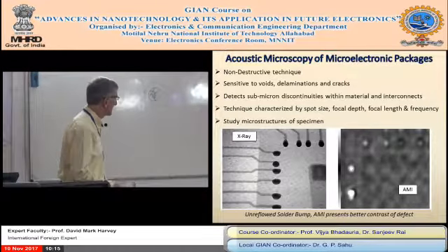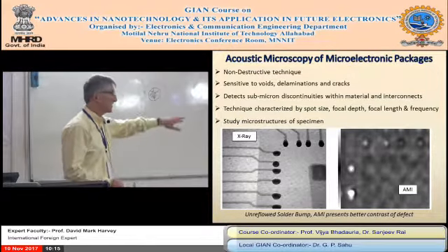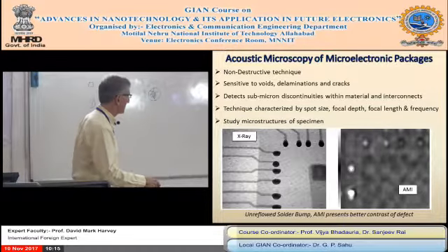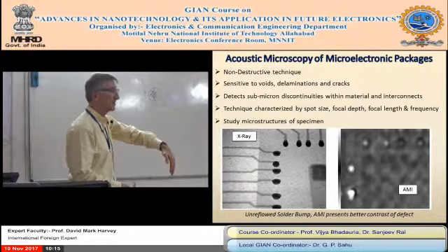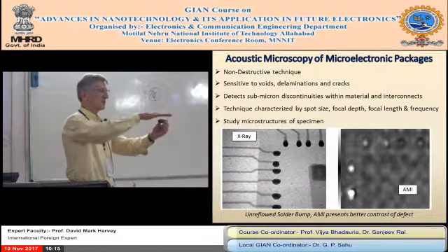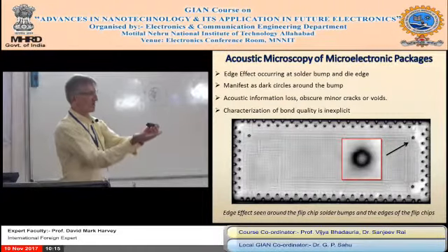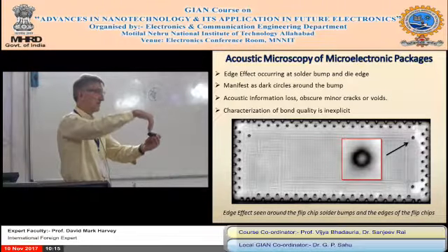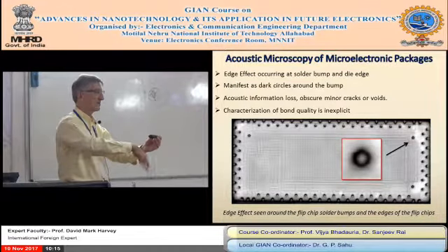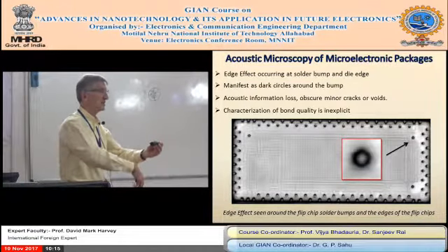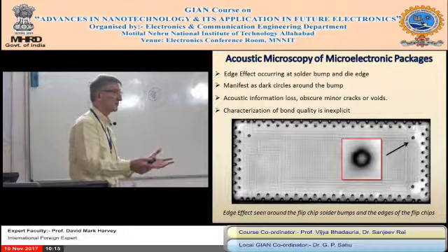It's a difficult one. AMI is able to detect the hidden defects also? Yes, all these are hidden under the joint. They're all hidden. Yeah. Here's a picture. This is our flip chip I've been talking about yesterday. 109 joints. This is looking through the top of a chip. So we've got the top of a chip which is like a shiny silicon surface. 109 solder balls underneath. So we go through the top and can detect the joints underneath and anything. And we can penetrate down to some point, then all the sound is reflected, so you can't penetrate any deeper. So this is a problem. As the frequency goes up, you can't penetrate as deeply. It gets dispersed through all the different things.